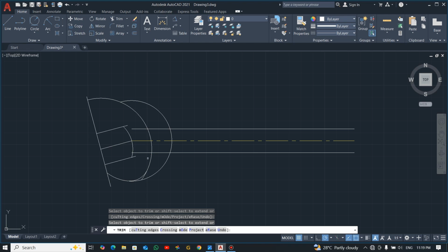You need to trim carefully. Good. Now if you watch, we trim that side, we don't need to. So if you watch carefully, we need to apply this 16. There's another one here, 16. Okay, so tan radius, click this and this, and then 16, and then you trim the inside,